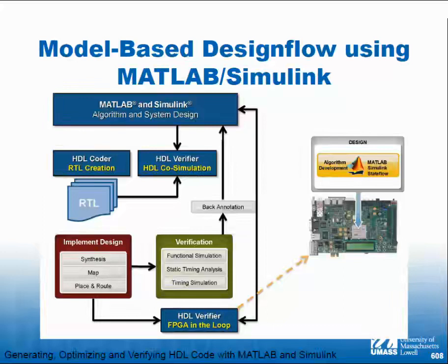Well, that's what this is doing, but it's doing it more automatically. So we have clear models for what the design is captured in. That's MATLAB Simulink. Then from there, we go into this HDL Verifier. Now, HDL Verifier takes the model of the design and it allows us to create at least the shell of a test bench. So now we have a design that has stimulus and response in it.